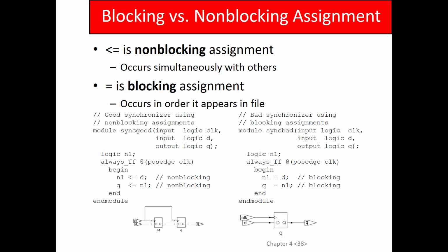Why? Because N1 would be set on the rising edge of the clock, and all always statements that are sensitive to the rising edge of the clock would see that change right away. Make sense? It's hard to explain, and I always run into trouble with this, which is why it's best to follow the convention. Make sense? Yes? So in the event of a blocking statement, does this imply it's going to wait the number of cycles necessary for that state to propagate?